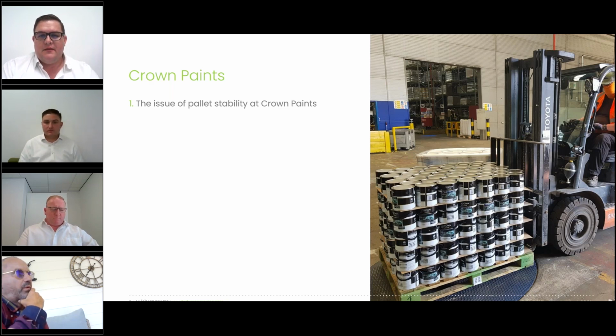Yeah, I mean, early we tried to fix the problem and probably didn't fix the problem. We had a long-term issue with movement in transport with our 10-litre buckets, probably to the cost of £200,000 a year. 10-litre packaging used within the UK industry, certainly the paint industry, is poorly designed, and the stacking configuration sits inboard of the pallet, creating a gap when loaded on the vehicle.